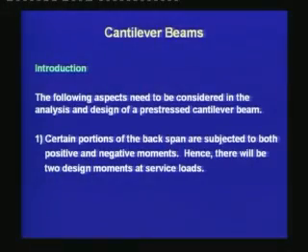The following aspects need to be considered in the analysis and design of a prestressed cantilever beam. First, certain portions of the backspan are subjected to both positive and negative moments. Hence, there will be two design moments at service loads. In a simply supported beam, we had seen that throughout the length, the beam is always subjected to a positive moment due to gravity loads. But in a backspan of a cantilever beam, the same section can be subjected to a positive moment or a negative moment depending on the loading condition. Thus, we have two values of design moments for most of the